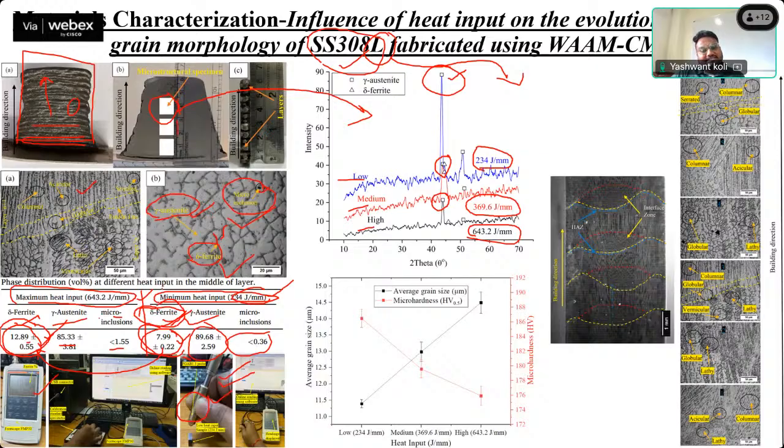In the boiler industry, it is needed that 10% or 8 to 10% ferrite should be there, because it can prevent transgranular corrosion and stress corrosion. So the corrosion part has been reduced by this ferrite content. If it is completely absent, then there is a problem. So the ferrite inclusion has an advantage also.